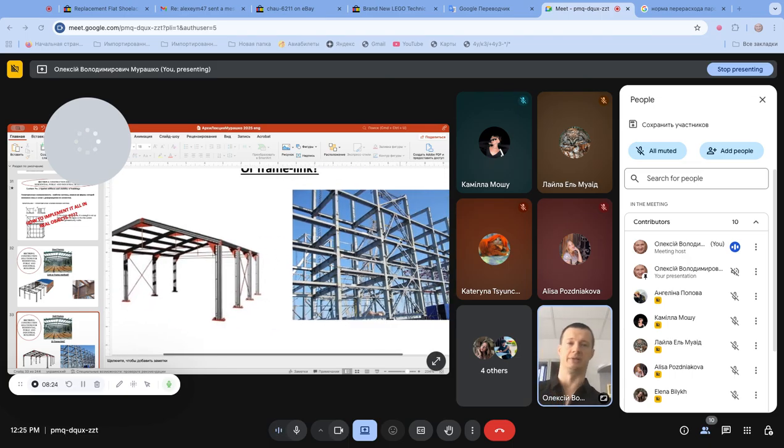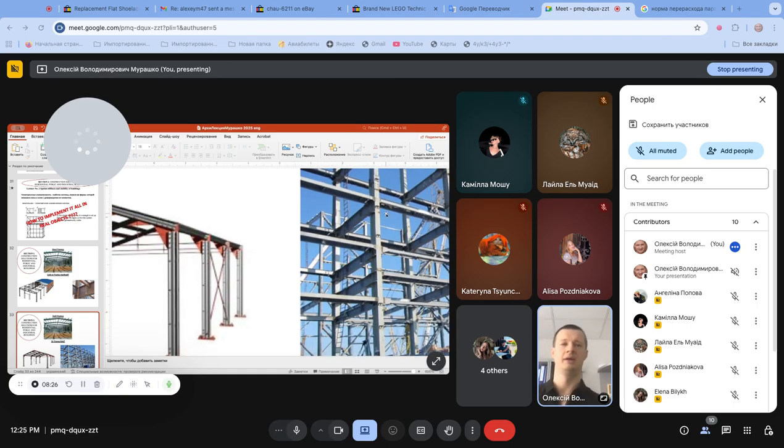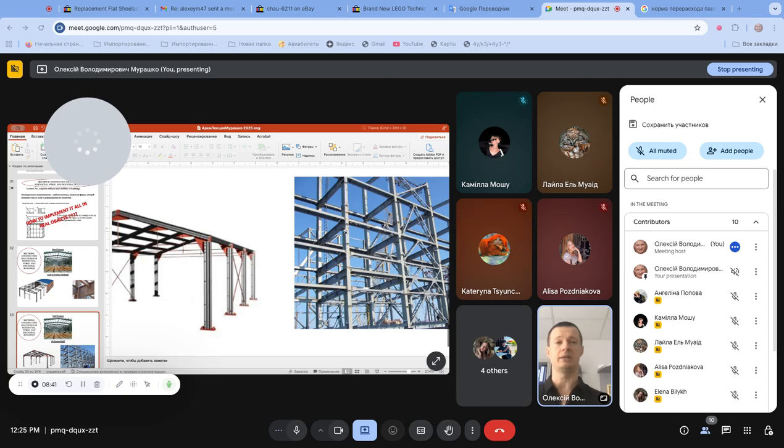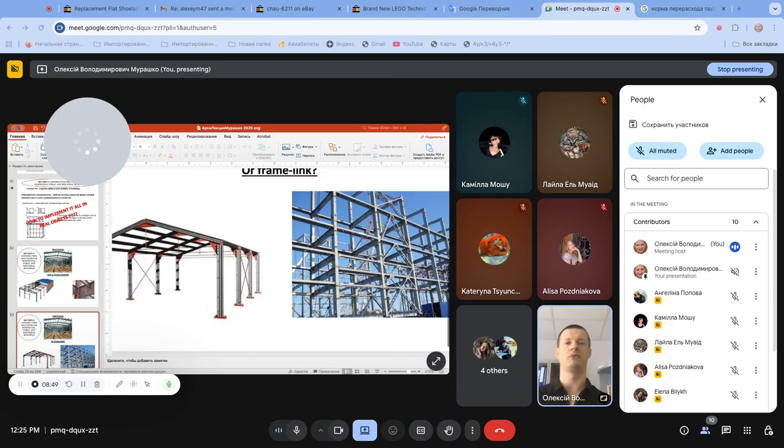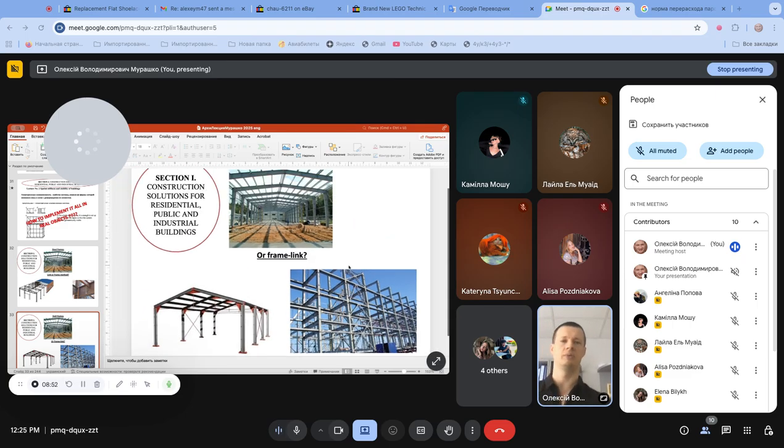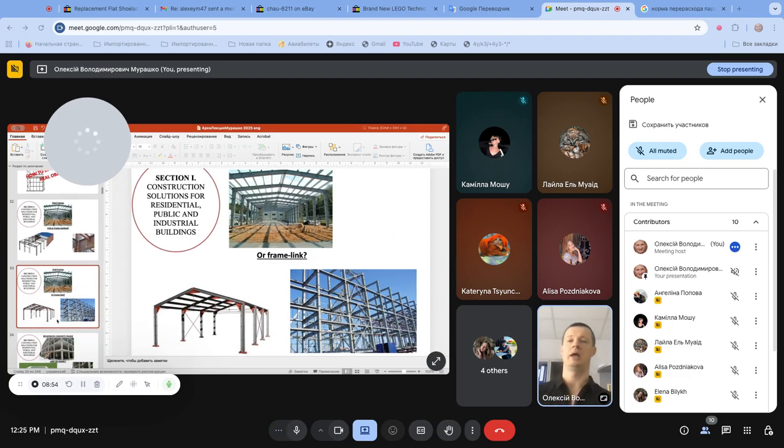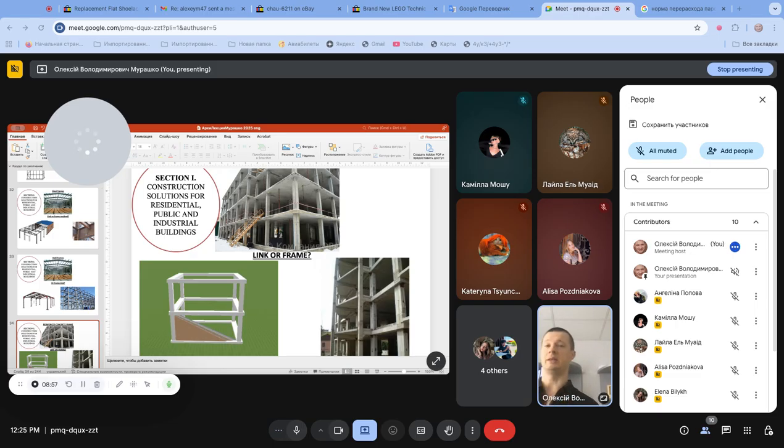In this case, this was made for symmetry. When we're considering this building, you can see how big the section of this beam is, and the connection between this beam and this column. So that makes us understand that in this direction, along this beam, they have made a rigid connection, and along the building they have added these links. So it's a mixture of the frame method with rigid connection of the elements and the link method. And that was when we were considering steel frame.